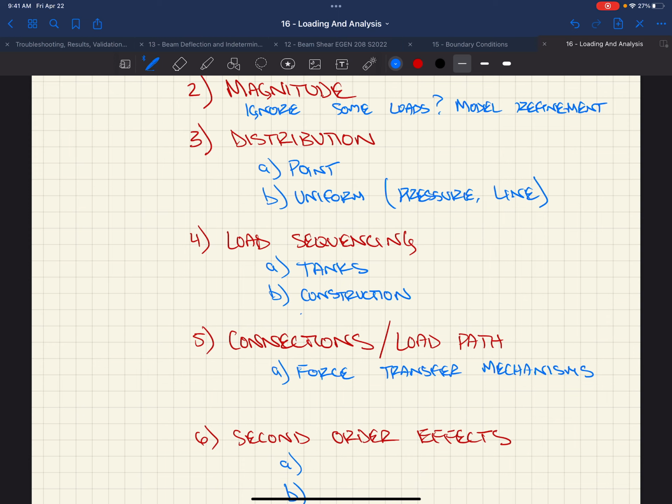So you end up putting joints in the slabs, right? Because concrete cracks, it shrinks. We can put control joints in the slabs, we have construction joints. Obviously, they can't pour one big continuous slab, right? There's a limit, so we end up putting joints in it. At these joints, sometimes we might have a joint that goes across here, and we might put a dowel across it, okay? And that dowel across it, we might have it deformed, just take a piece of rebar and put it across the joint.